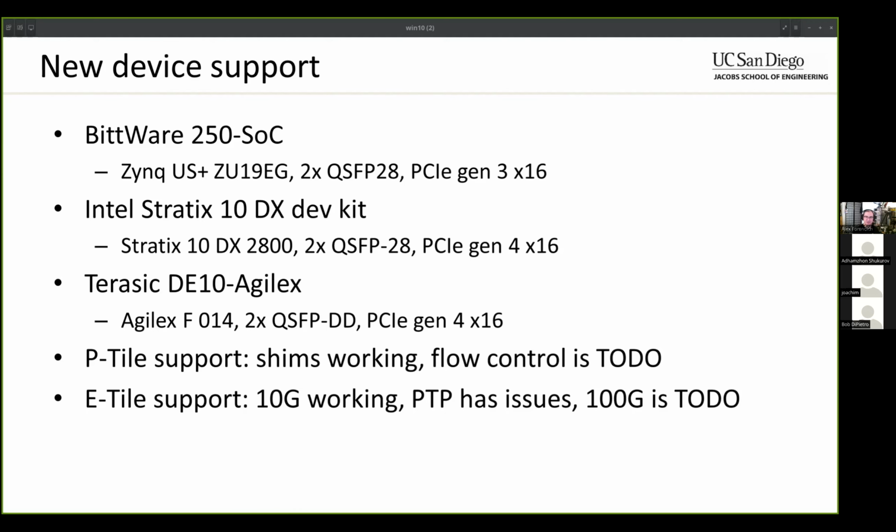So I need to build a new design with those parameters updated, and I'm also going to revisit those same parameters on the Xilinx devices as well, because I think the particular values that I'm using for those date back to before flow control was implemented, in an effort to avoid head-of-line blocking. So I have a very low limit on the number of in-flight writes.